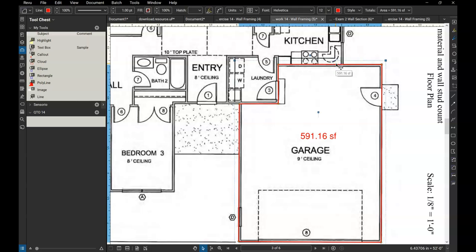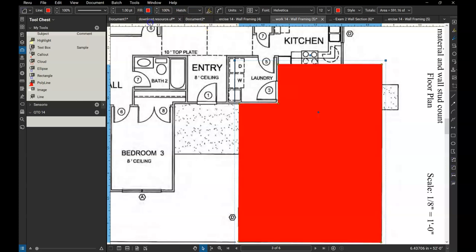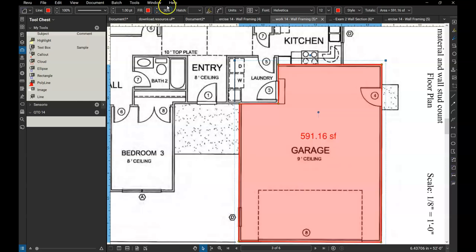So with that highlighted too, again by default it just creates a red outline. It's not filled in. So once you're done with that one, go ahead and let's fill it in, color of your choice. But we're going to down the opacity. So pick a color, and then right next to it is the opacity, or how bold it is, or how filled in it is. So I'm going to down this to like 30%, just so we can see what's behind that takeoff.